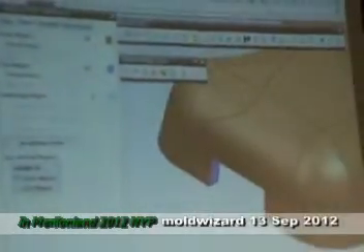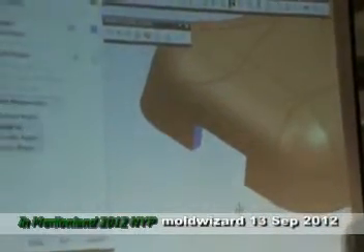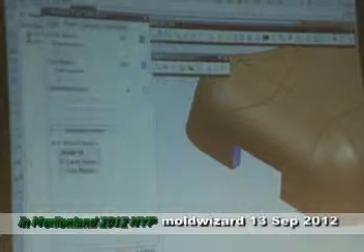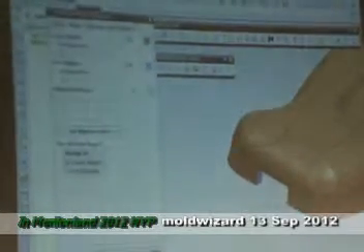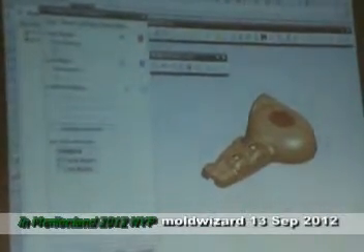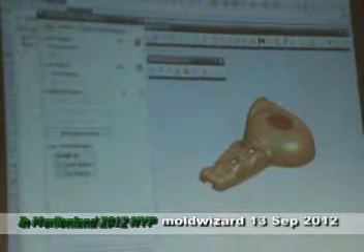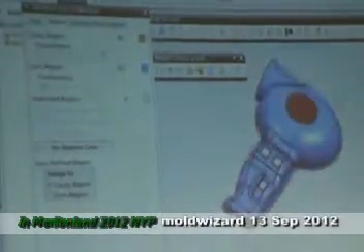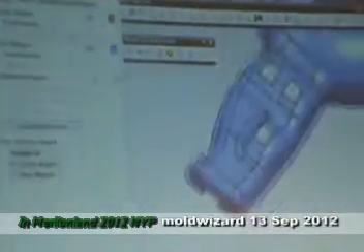That means I need to create a profile on the core insert, might be protruding out. So I need to create another profile recess in the cavity insert. And these two dimensions must be matched, must match to stop the plastic. So now this one okay. Just like what we did yesterday, you can try to change the color and take a look. Check. Always check.